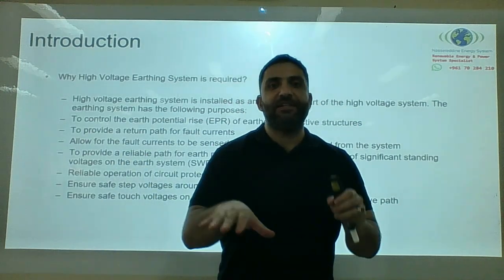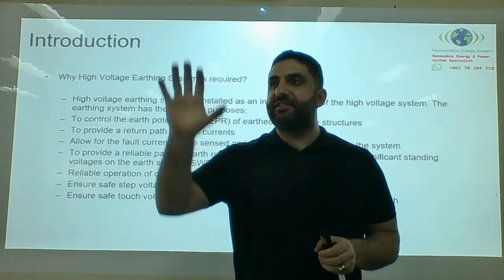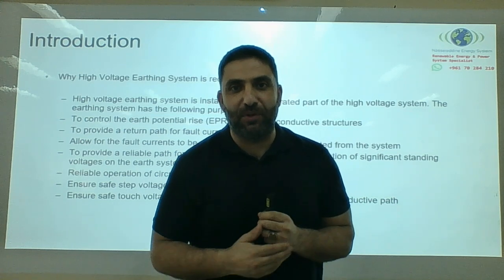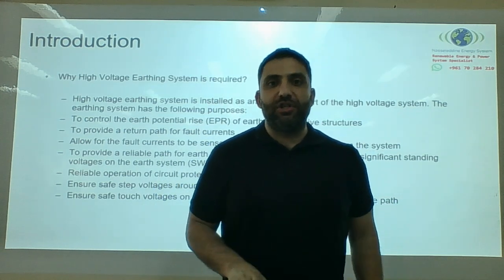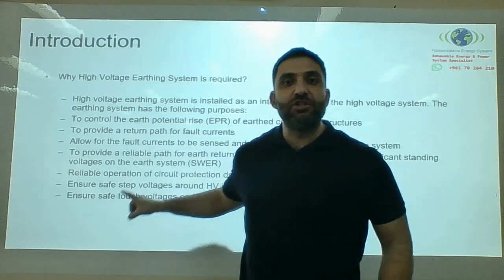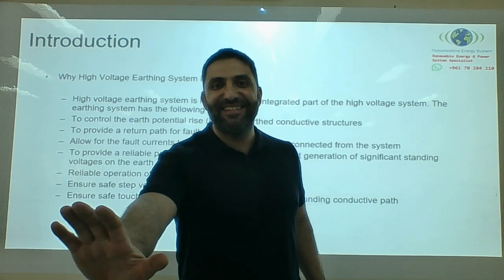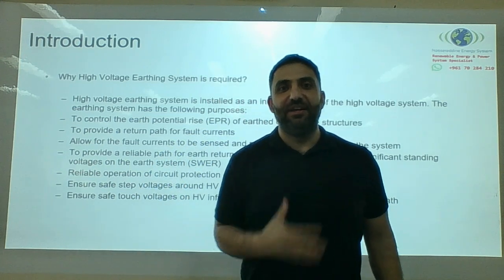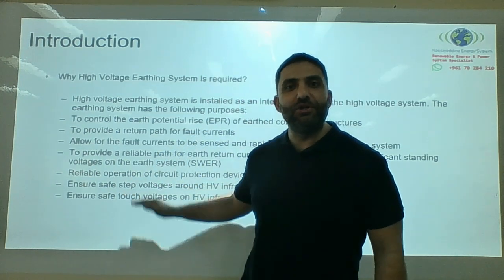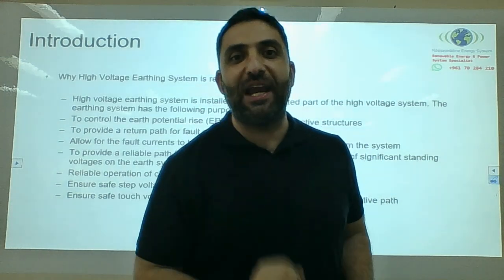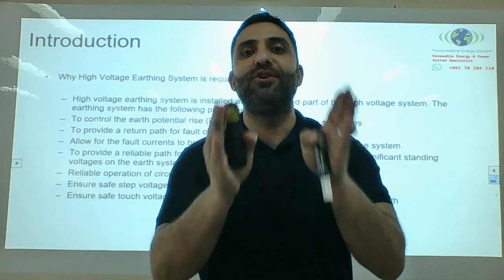If you live next to a high voltage infrastructure, or there is a tower or a high voltage pole in front of you, under fault condition, your conductive fence, if there is no adequate earthing system, if you touch the fence, you could get electrocuted. Your earthing system will ensure the step and touch voltages are below the allowable safety limit to keep you safe.